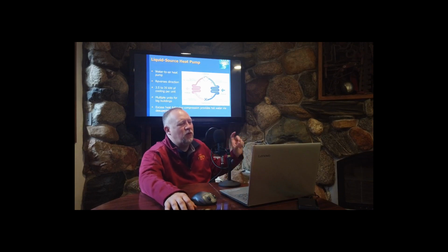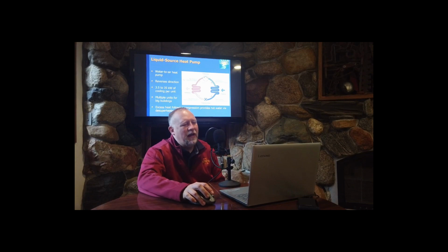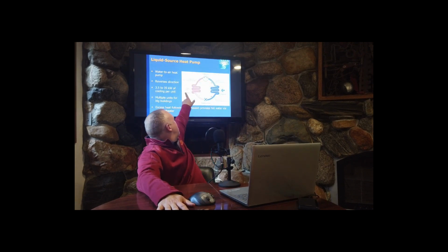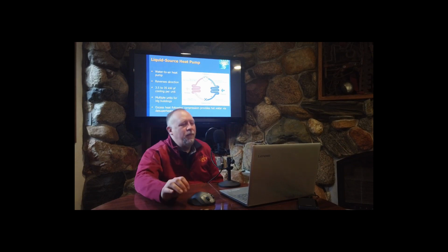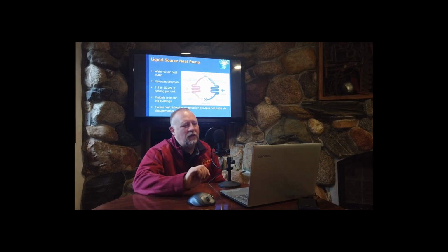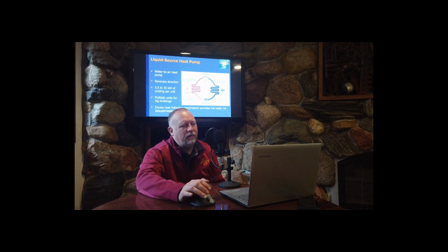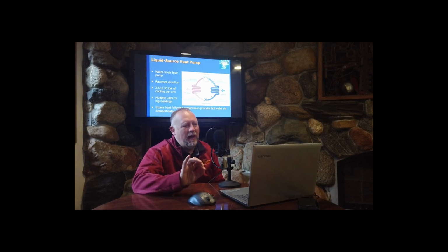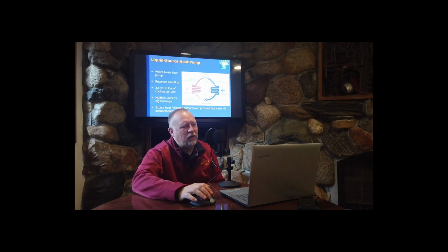The heat pump, I want you to think of it as the heat pump can just switch directions on where it's sending that high temperature vapor. All right. And that's it. Sometimes you'll hear this term, it has the ability to reverse the direction of the hot refrigerant. The compressor doesn't actually spin backwards. It just, through piping and valves, can automatically reverse the direction of the refrigerant. All right, let's keep going.